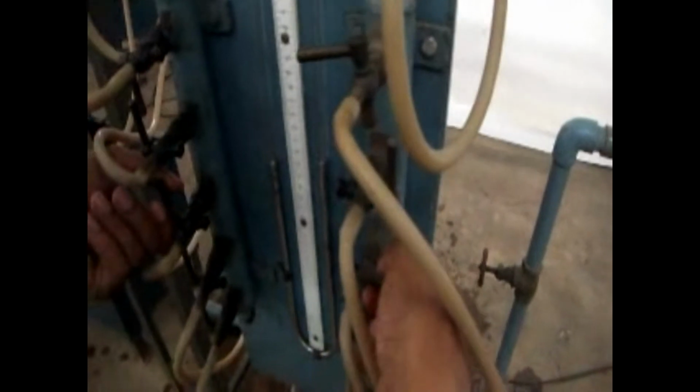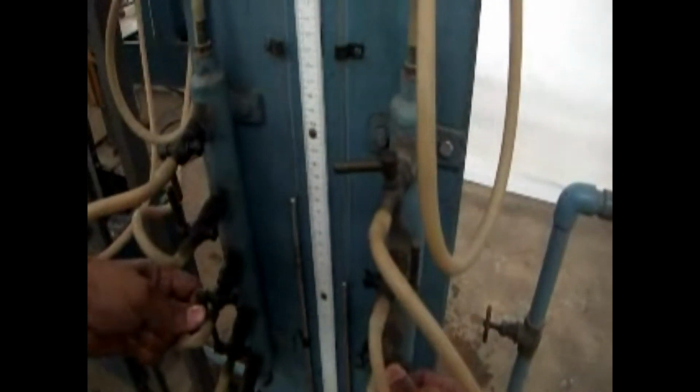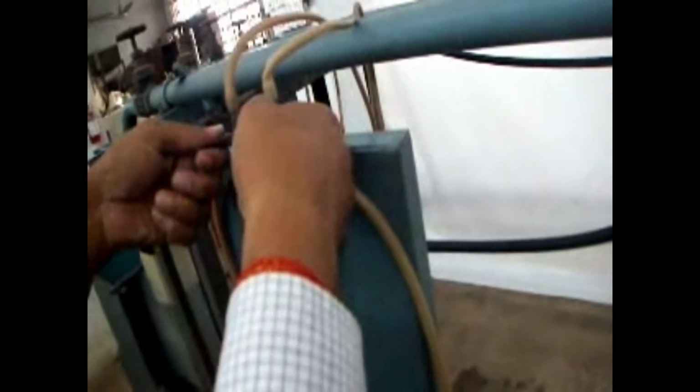So let us see the head difference for this first pressure, and let us see whether there is any air lock or not inside. So remove any air lock, so we can see water is supplied from both the sides, so there is no air lock. Now let us close this at the same time to find out what is the head difference.